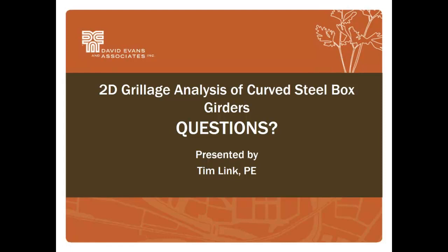So one question was, was the barrier rail included just for the stiffness model, or was it also included in the structural capacity used in the rating calculations? And what was the justification? So the barrier rail element, its primary purpose, one, was to connect the cantilever deck elements together. The other purpose was so you had a reference beam element for defining the exterior girder lanes. That way you could easily just have a constant offset from that element for your lane placement.